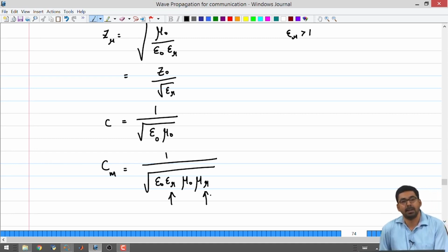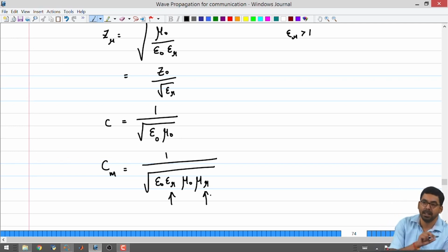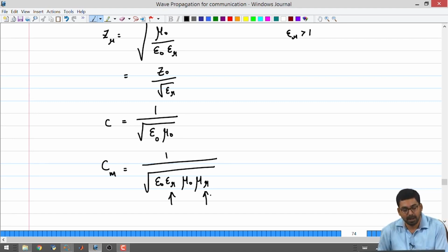We also saw this with the transmission line. There was something known as velocity factor in the transmission line specification. It was written that the speed is 66% of the speed of light. It was not written 200%. So, the maximum velocity that you will always have in these cases is the velocity of light in vacuum. So, there is always a finite velocity upper bound, and any other medium will always have lower velocity, and most likely they will also be having lower values of characteristic impedance if they are non-magnetic.